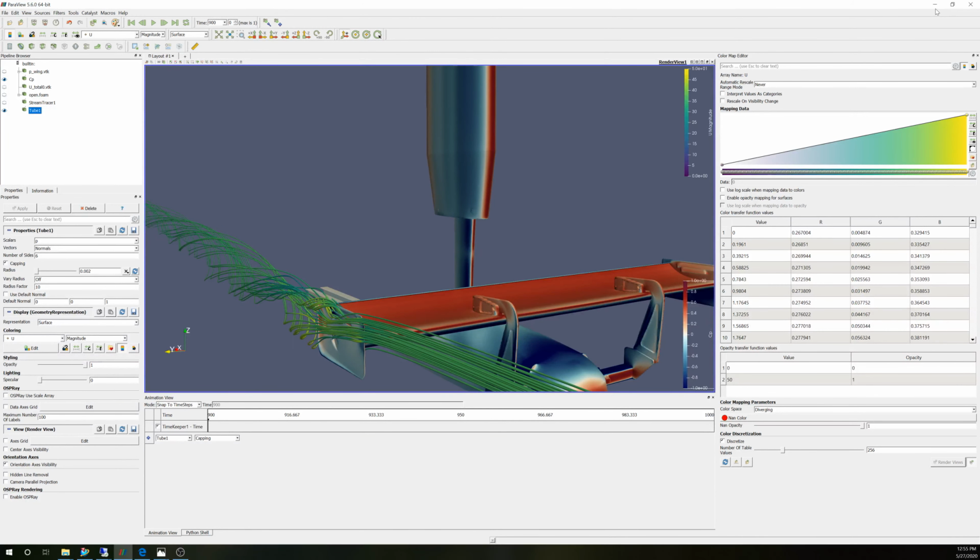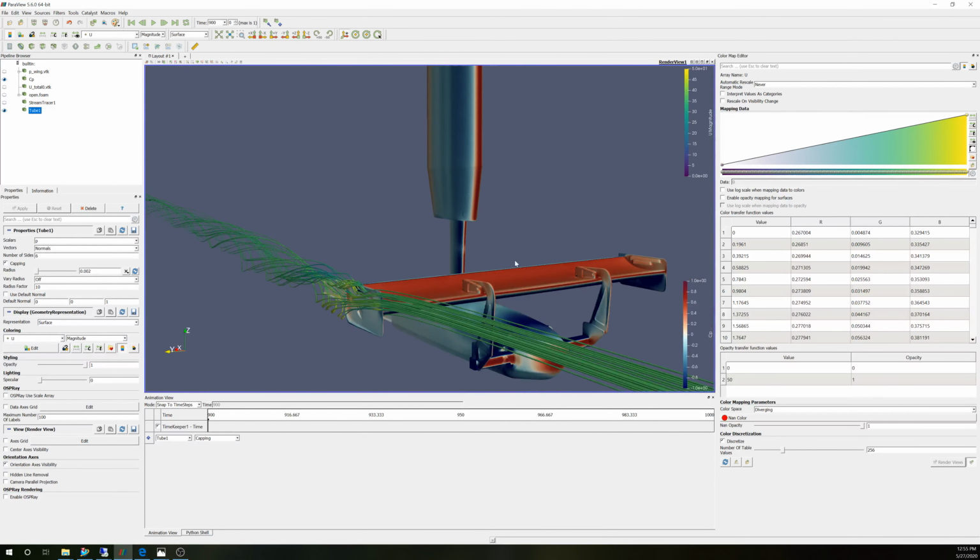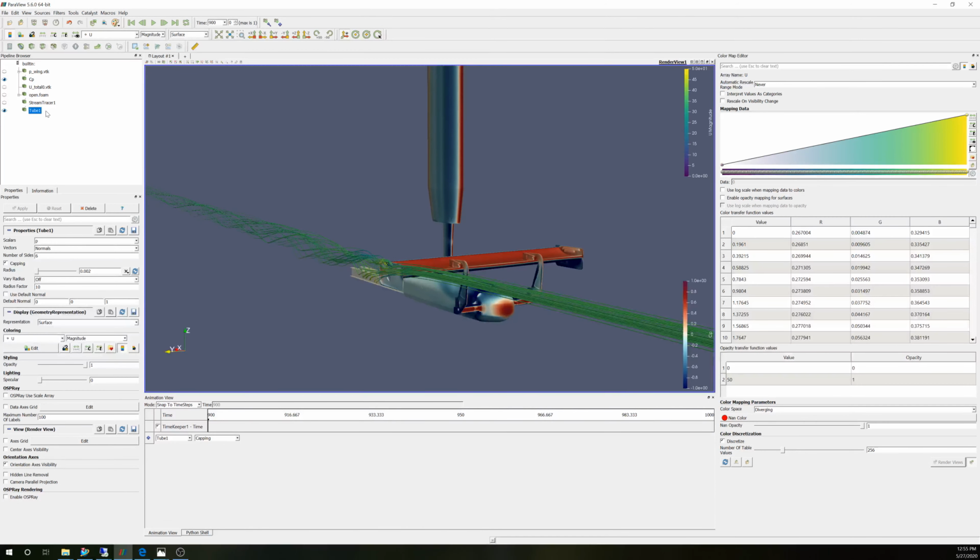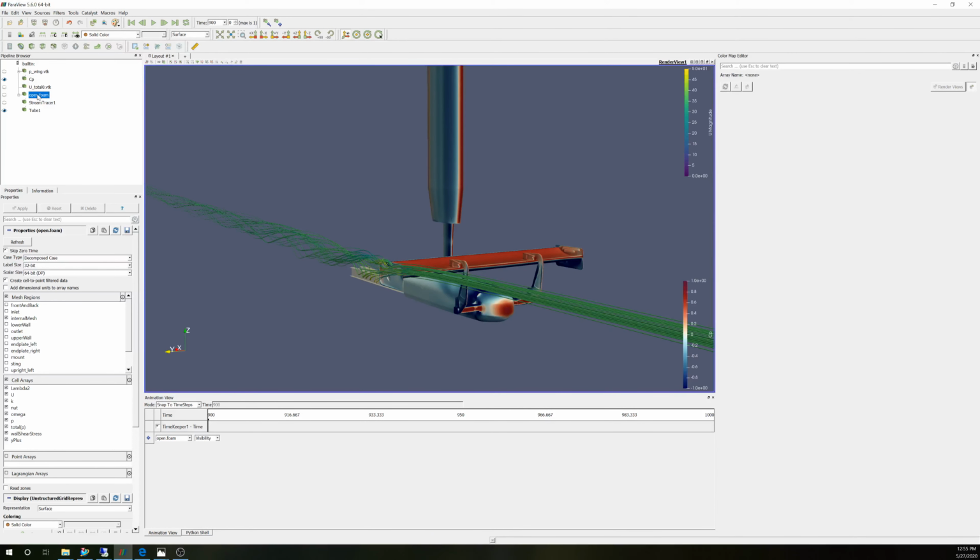Let's see, we had some questions on Instagram. The wind tunnel wing looks pretty close to the ground, as shown in CFD. Was there a pressure gradient on the floor boundary condition? It looks close, but it's really not that close to the wing itself. To the contraption it is. Let me see if I can pull out... I didn't pull the floor, but I do have the full model here. Let me pull the lower wall. I'll add the lower wall in so you can see how close it is, and how the pressure is affected.